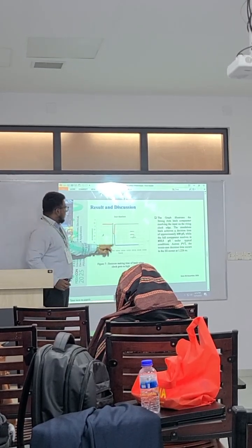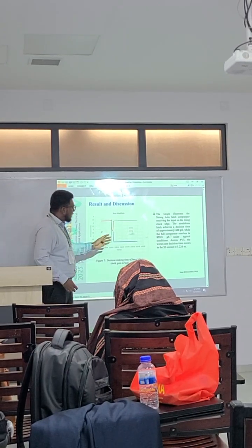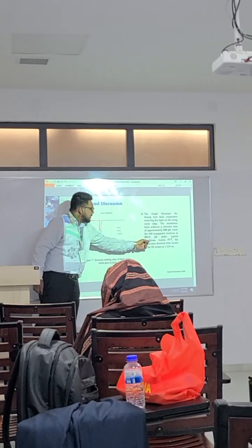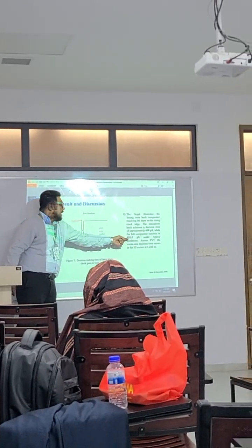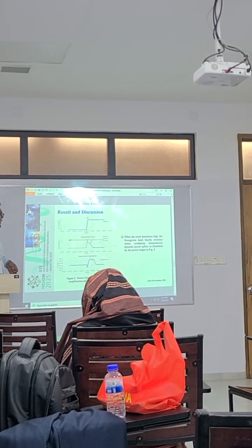This is the regeneration time, basically the propagation delay. So the latch comparator takes only 600 picoseconds, and the whole system takes around 855 picoseconds in the typical corner, and in the worst corner 1.226 nanoseconds.